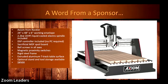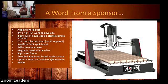So this is one of the CNC machines that's offered by Rockler. The brand name is Axiom. This one has a 24 by 48 bed with 6 inches of Z. That's typically about what you get, 6, 8 inches, something like that. There's usually not a heck of a lot of Z. It's a higher end spindle. You can see it's liquid cooled. It doesn't require a little PC. They've got a little embedded dedicated computer that runs the machine.